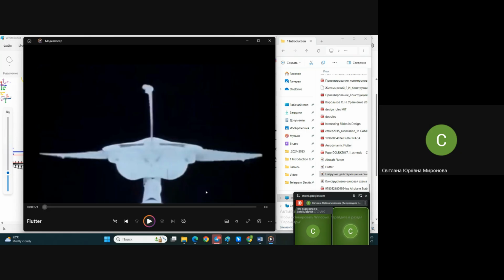One more way is to change the stiffness and center of gravity of the whole control surface by adding additional side structures to it. These balancing structures change the ability to bend and the ability to twist of the whole structure altogether.